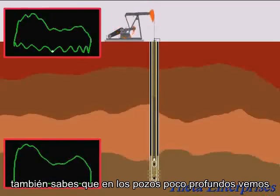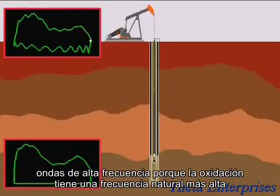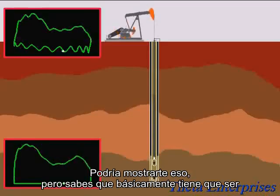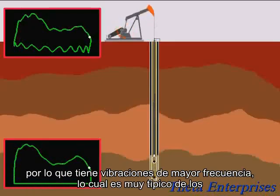Also, in shallow wells, we see more high frequency waves because the rod string has a higher natural frequency. If I had that slinky that Andy was playing with yesterday, I could show you that. But it basically has to do with the rod string being stiffer, so it has higher frequency vibrations. That's very typical for shallow wells.